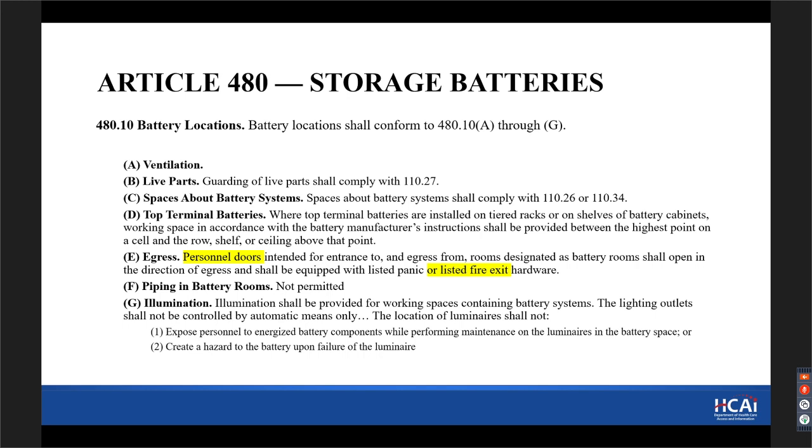And again, just like our electric rooms, there's requirements for guarding of live parts, space around batteries, egress requirements, personnel doors that open in the direction of egress, and with listed hardware, panic hardware.